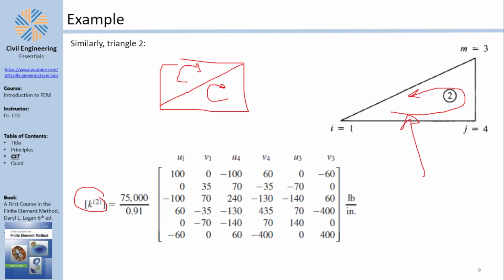I think you remember from previous videos, there is something called a transformation matrix. And usually we have done this whenever 2 elements had different orientations, so that we take the cosine and sine of their orientations with respect to the global axes, to the global sense. So basically the transformation matrix is a transformation between the local and global axis senses, or vice versa, depending on the transpose or not. So you would think, okay, where is the transformation matrix in all of this? The answer is it's not needed.